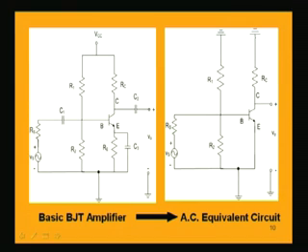Now, after this, we have to see the capacitances which are offering short circuit paths under AC. That is because we have chosen C1, C2, C3 to be large enough, and that has to be kept in mind. For designing this amplifier, we must pick values of C1, C2 and C3 conveniently large enough, so that equivalently we can draw them like a short circuit. That is being done here. Instead of C1, C2, C3, we see that these are short circuited paths. C1 is a short circuited path, C3 is short circuited, and the coupling capacitor is also a short circuited path.